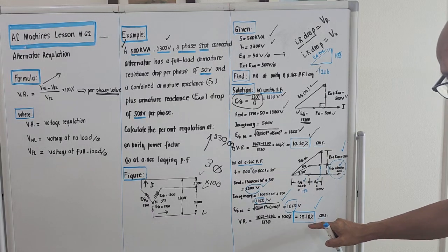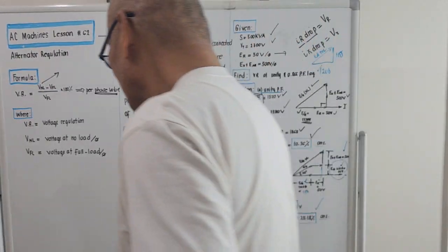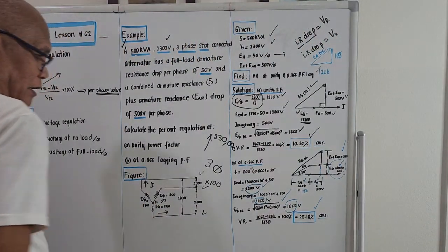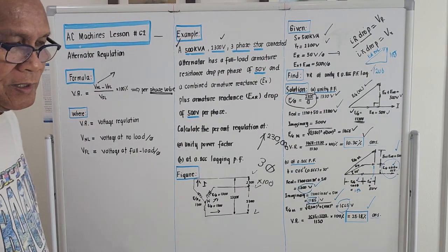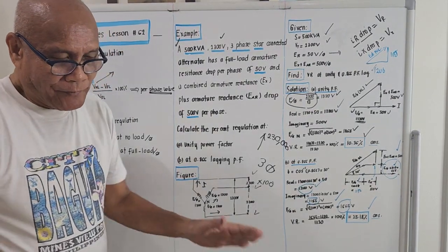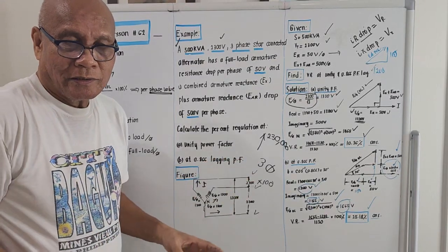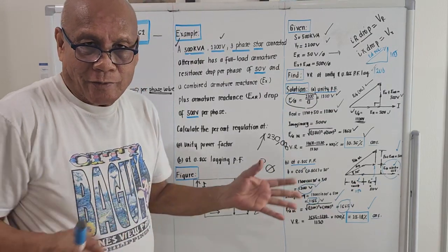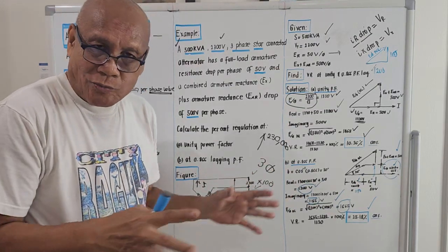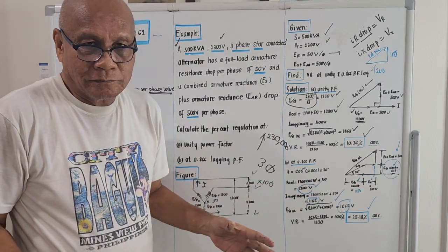This is high. Okay? The alternator has a very hard work to generate voltage if the loads are actually motor loads. That's why sometimes utility companies want us to shut down our air conditioners during peak hours because the transmission lines are actually overloaded, or the alternator could be overloaded.